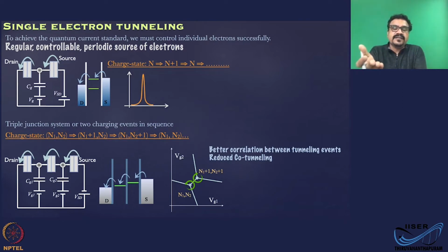and next you can actually make this electron tunnel out to the source, and you can also make sure that this electron doesn't tunnel back to the first dot just by adjusting that gate voltage using voltage pulses. So that is the overall idea.